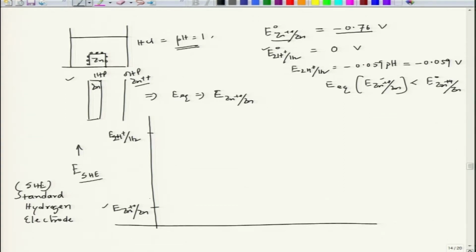Now, in that case of course their level would be like this, but here the value would be decided by the concentration that the zinc metal is facing in front of it. Now, it will have its own polarization. Individually we will have polarization like this. This value is I0 zinc on zinc surface, and similarly I can have I0 hydrogen on zinc surface.